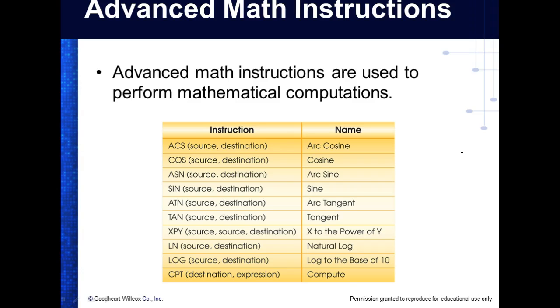In the old days, we used to use analog generators. The faster the motor ran, the more voltage the little generator would put out. We call them tachometers. And then we had to take that and bring it into the PLC, and then we had to convert it to what? Digitally. So more and more we're using what we call encoders, which is nothing but a wheel with a bunch of slots in it, spinning and sending digital what? Pulses. And you get some of these DC motors and some of these AC motors up to 7,000 revolutions per minute.